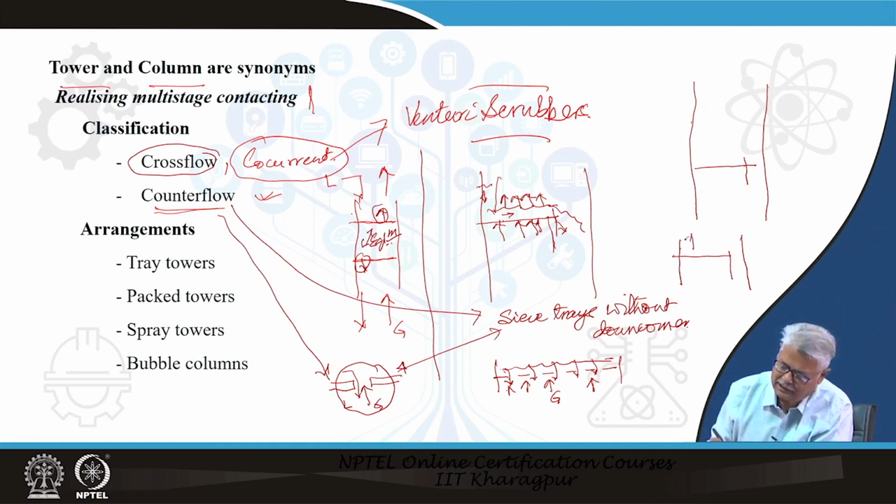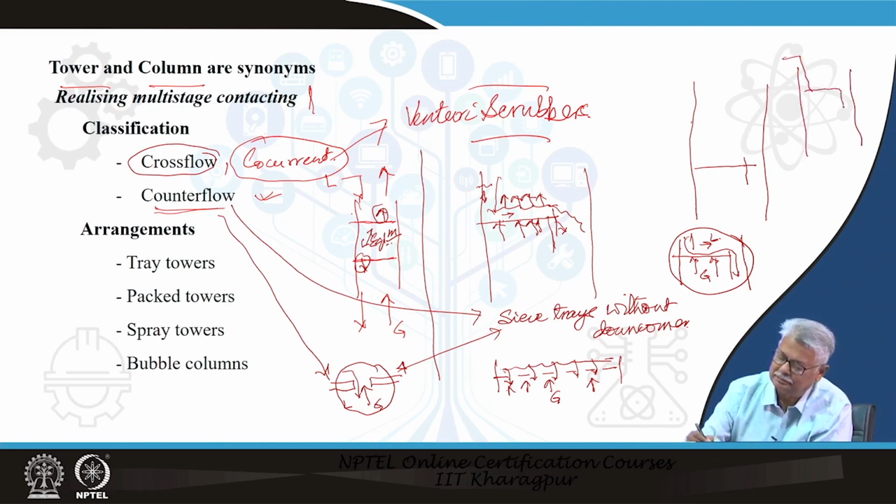The upper downcomer ends here, the liquid flows across this and falls to the lower tray. And this is your gas stream and this is your liquid stream. Now, you have such trays placed one above the other. That means, in the tray, the part of the liquid which comes from the top is something like this. And finally, it comes out. The part of the gas is rather direct. It passes through each of these liquid streams, it bubbles through the liquid streams and goes up.